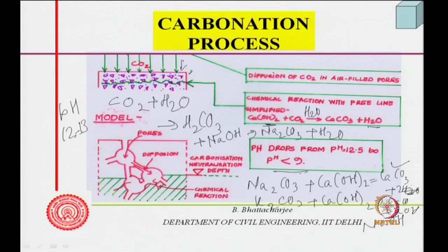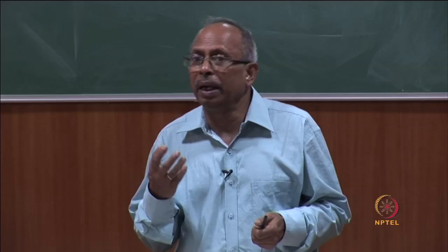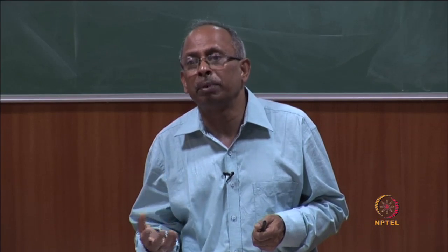So, calcium hydroxide provides a kind of reserve alkalinity. Sodium hydroxide and potassium hydroxide do not get consumed initially, they are just the in-between steps. They react with carbonic acid, which is formed because of the carbon dioxide coming from the atmosphere in the presence of moisture. This reaction can proceed, and sodium carbonate can react with calcium hydroxide, forming calcium carbonate.